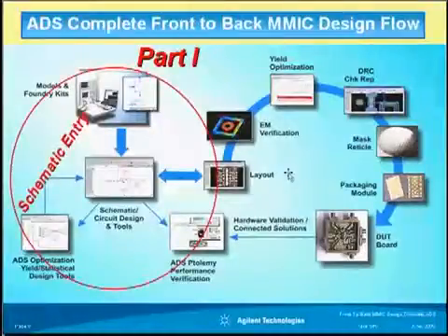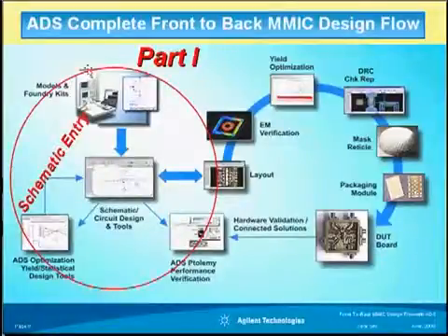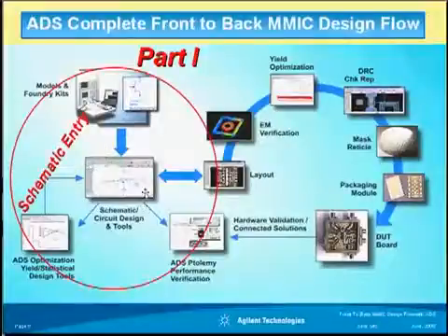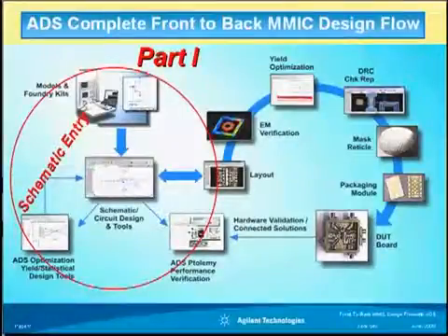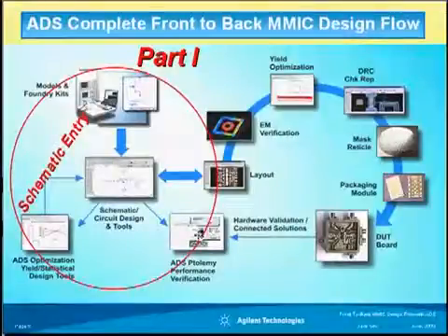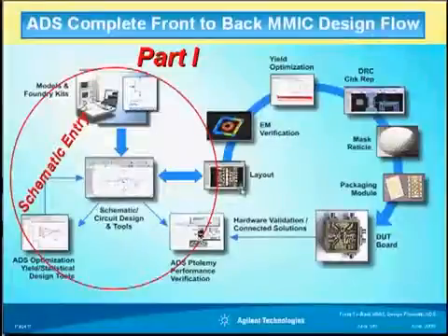Part 1 of this presentation now will focus on the schematic entry of the design flow. So we start from the models and Foundry design kits, then we have our schematic entry design, then we use the DFM tool, the statistical analysis, to convert our design into a solid, robust design, and then we will verify it through wireless verification standards. And then we will move to part 2, which is the physical design aspect.